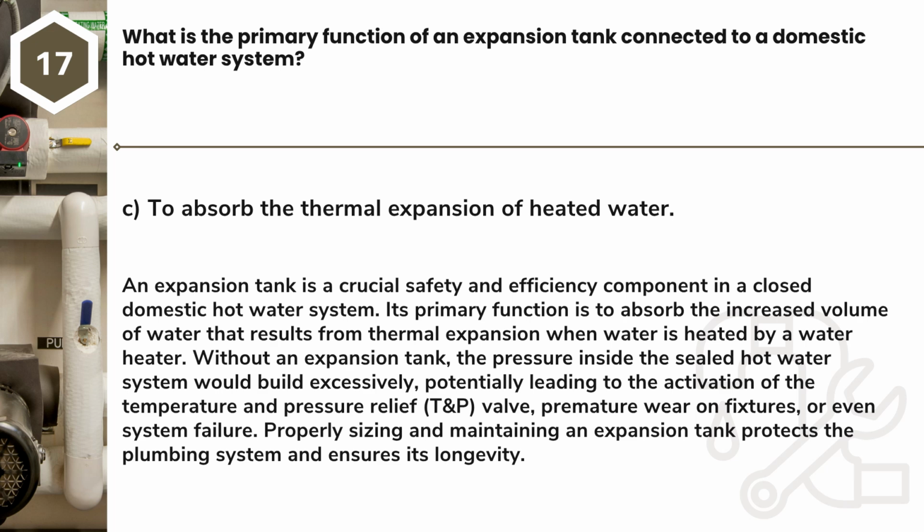Answer: C. To absorb the thermal expansion of heated water. An expansion tank is a crucial safety and efficiency component in a closed domestic hot water system. Its primary function is to absorb the increased volume of water that results from thermal expansion when water is heated